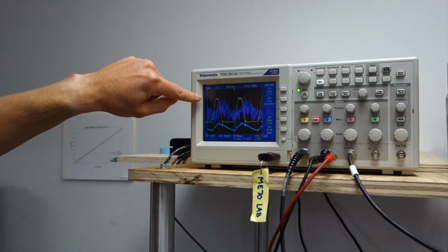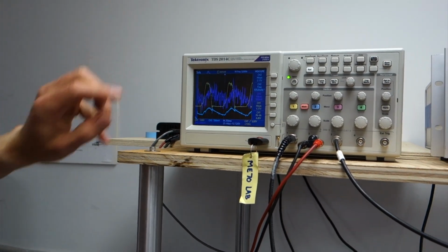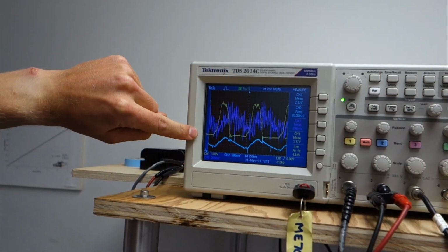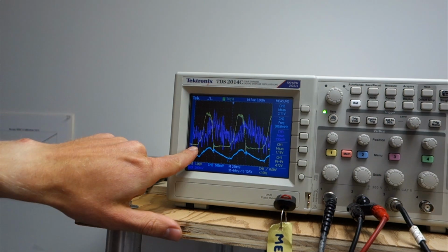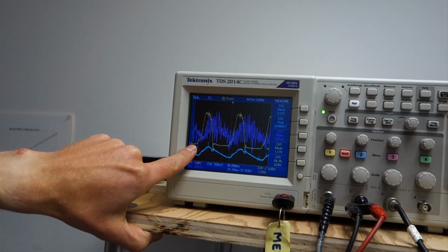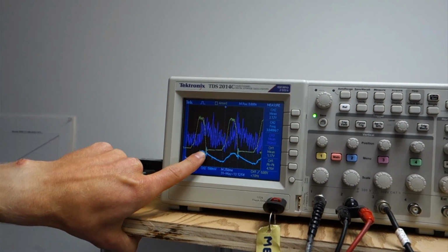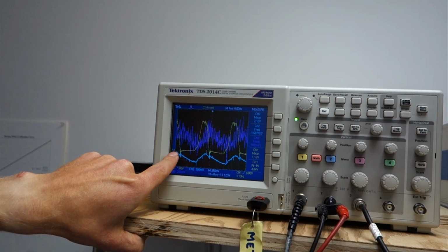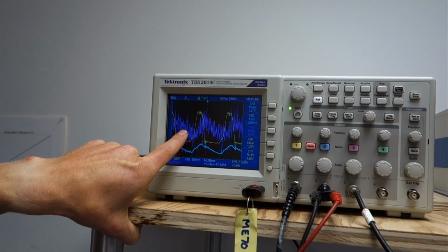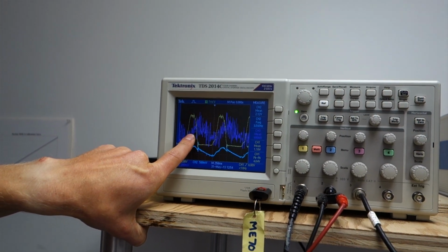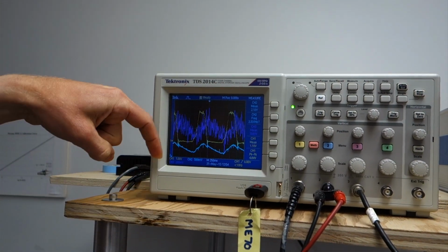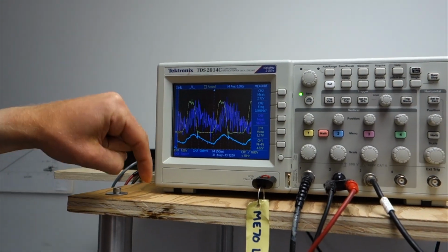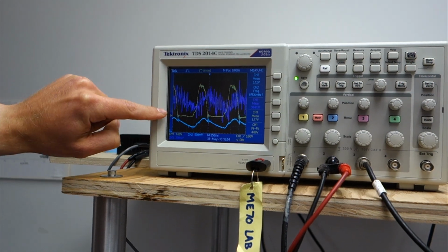Whenever you look at a scope, you need to understand what the zero values are. If you look at channel 1, there's an arrow that corresponds to the zero of that channel, which is right at that level, which means that there are regions of the flow where Q1 is equal to 0. In fact, Q1 is negative where there's retrograde flow. Conversely, channel 3, the purple trace, looks noisy, but really it's just zoomed in really far. The 0 for Q3 is below the 0 of the screen. You see a purple mark there, which signifies that the 0 is down there. So this is much more steady than Q1.